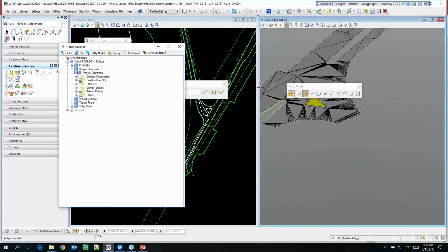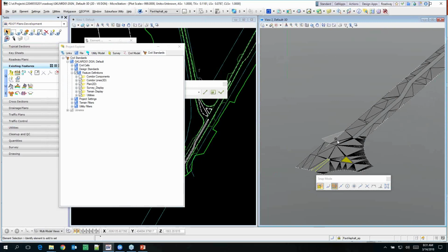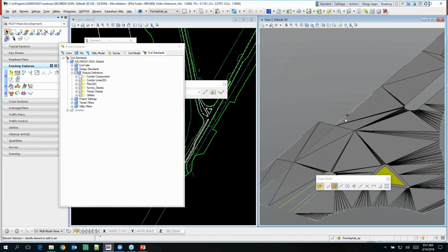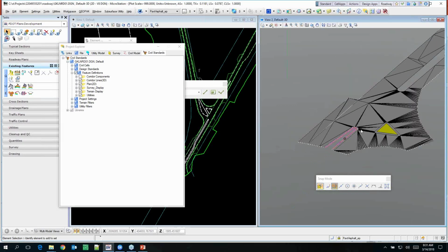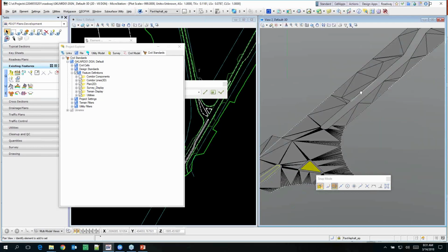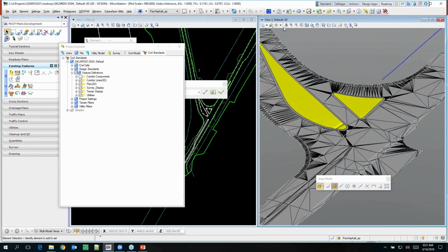And there's just all the top terrain. Is that the GDTM? That is the clippings from the GDTM. So you've created the shapes for the existing pavement, and then you've clipped it with this. This one is an external clipping boundary on the edge of pavement, and then internal boundaries cutting out the traffic separators, the right turn island, median, all of those features have been removed.